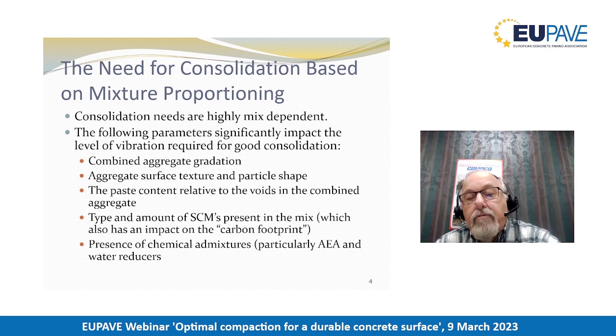The carbon imprint of that is going to be significant in pavement type selection, and moving forward, that is the direction we'll be taking. In addition, we also are switching to Portland limestone cement, or PLC. We have traditionally used type 1, type 1-2 cement. Now the only product that's going to be available to us, at least in the state of Illinois, is going to be PLC. We're making adjustments to our mixes to accommodate that, but there will also be resulting changes in